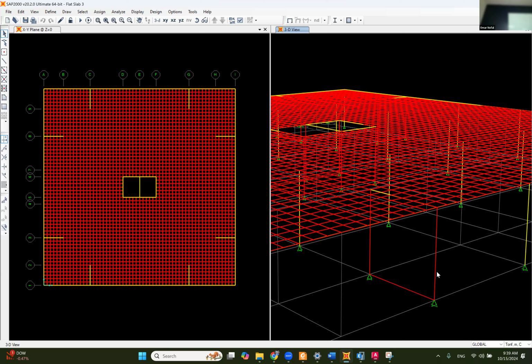This wall is not supported at the start and at the end. It has a foundation all the way over the length of the beam, either a strip foundation, or a pile cap, or something that goes from here to here. And if you guys remember, this is a very, very big shell. And if it's a big shell, the analysis is not going to be accurate. It's like 3 meters by 3 meters. So we need to divide it into a much smaller mesh. So this is note number 2.